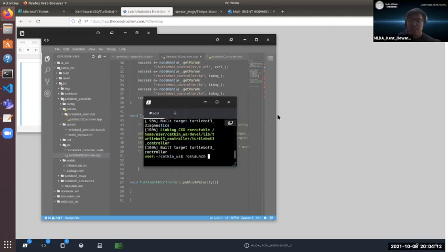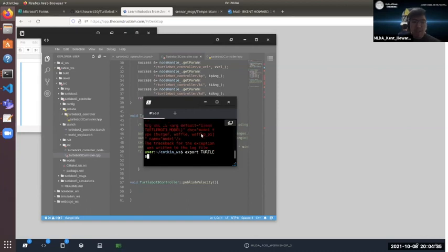So to launch our controller node, just remember to type roslaunch turtlebot3_controller, then just tab, and you hit enter here. Also one more thing you need to do is type this command, TURTLEBOT3_MODEL equals waffle. This essentially tells what model of TurtleBot you want to use in your simulation. In this case, we want to use waffle, and then we can launch the simulation in our ConstructSim.